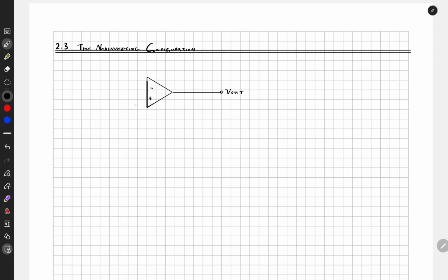So what we do now is we move the input signal to here, to this bottom positive terminal, and like before, we also have the feedback through the feedback resistor, but the difference now is that the signal path on the negative terminal side is sent to the ground.